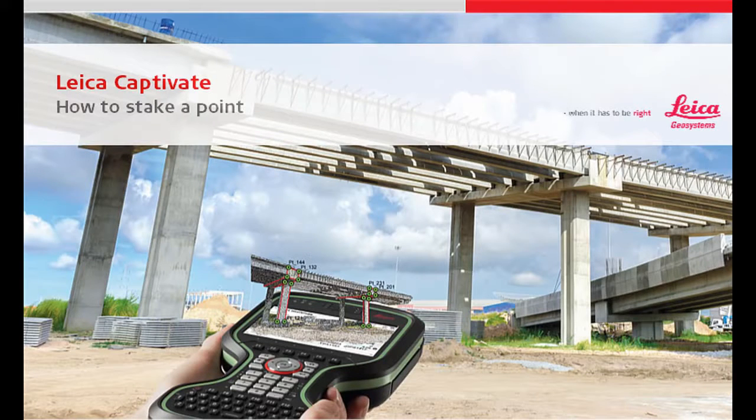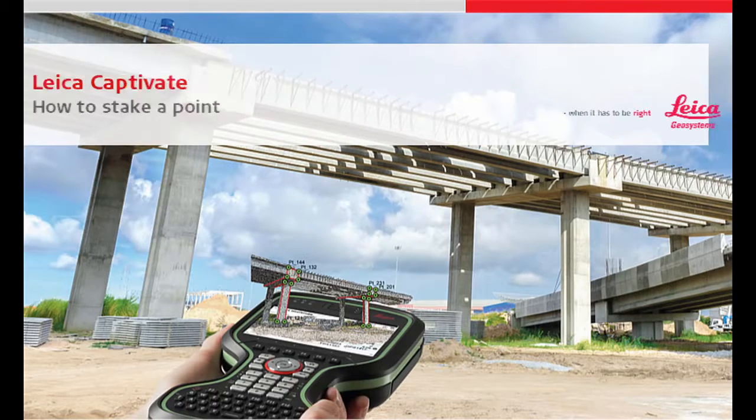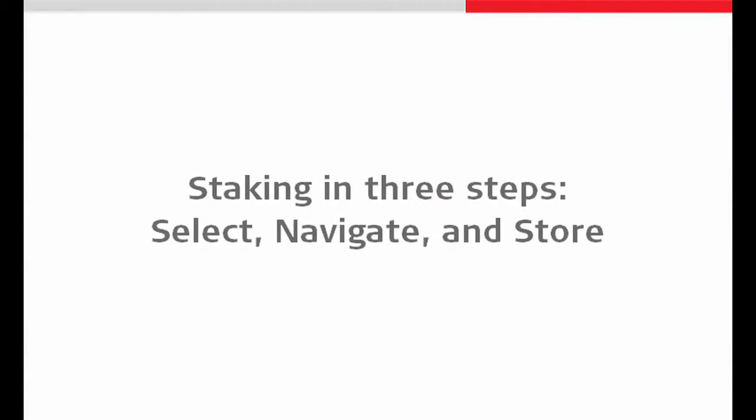In this video, we will look at how to select and stake a point using Leica Captivate field software. Staking a point should be, and is, a relatively straightforward process involving just 3 simple steps. First, selecting the data to stake out, then following on-screen navigation, and finally, storing the result.